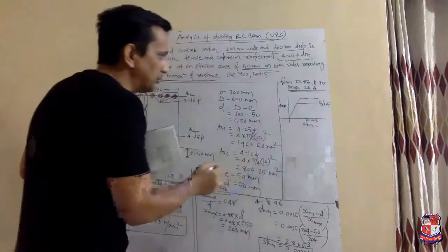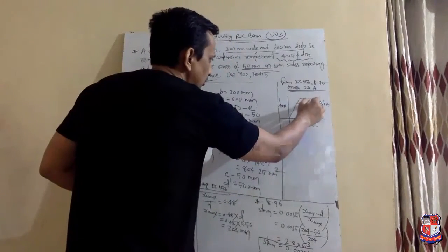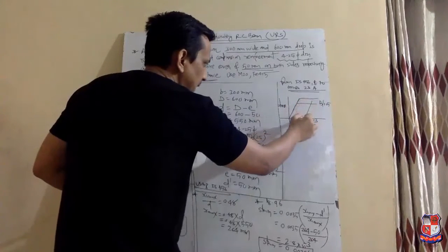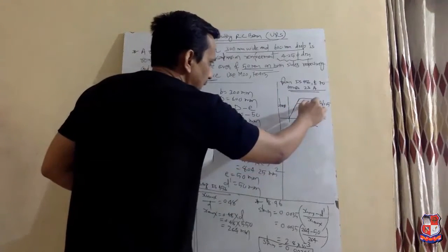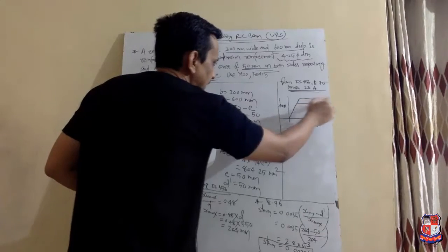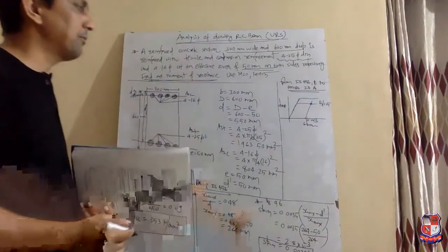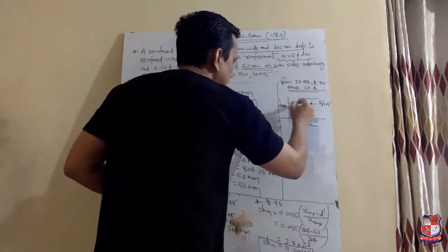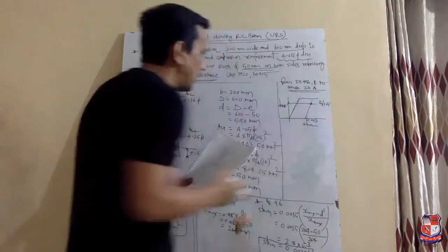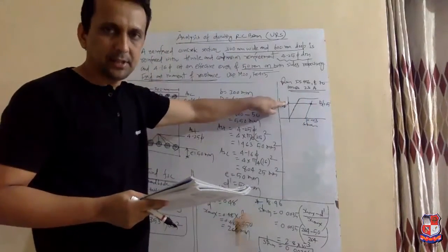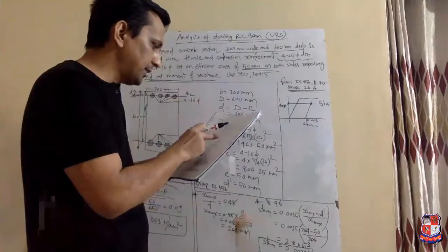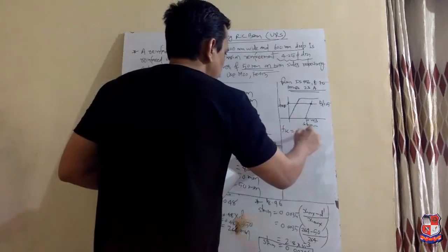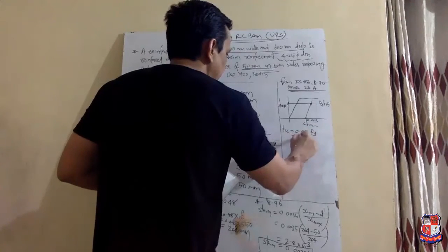First, you need to draw a parallel line with this line, and where this parallel line intersects the Fy upon 1.15 line, corresponding to that intersecting line, you have to find the stress value at vertical. So in our case, it comes FSC equal to 0.85 Fy.